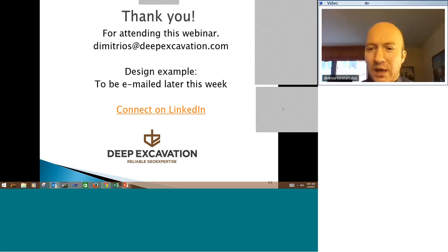Not really. There's a question, so it has to be finite elements. Not really. Finite elements is one option. Elastoplastic Winkler springs is another. And in some cases, finite elements might not necessarily produce realistic results. You tend to overestimate the basal movements and how much uplift you get on excavation. So it depends really how you want to analyze, but not only finite elements. We always recommend that you use at least two methods of looking at an excavation, and we'll always do that.